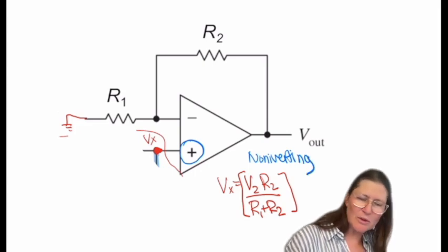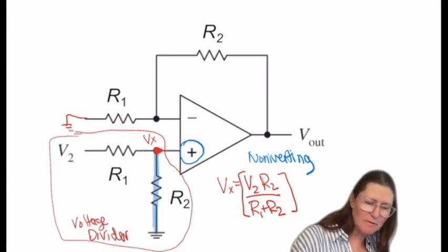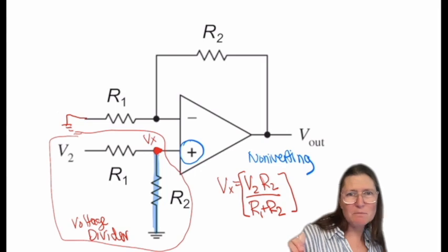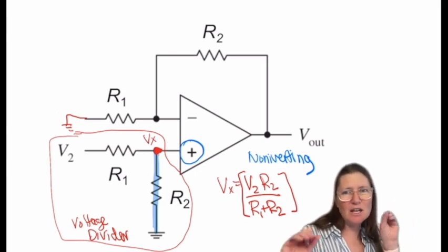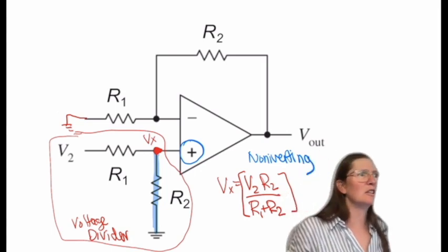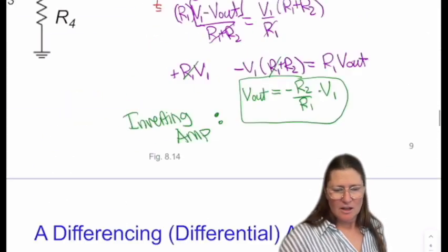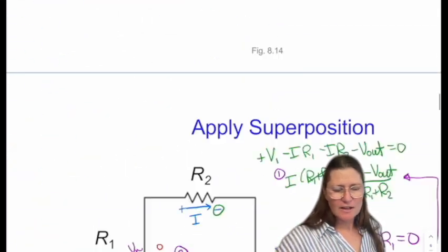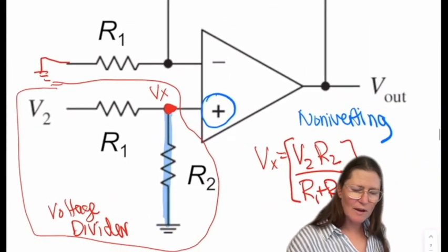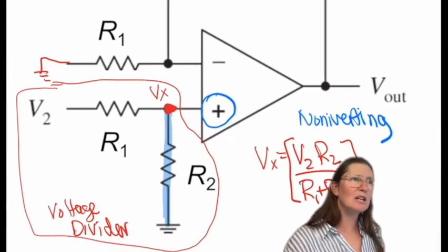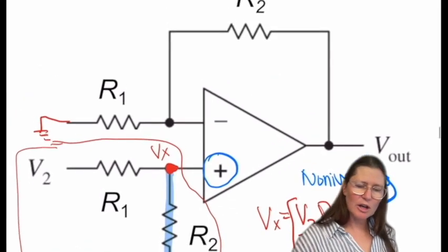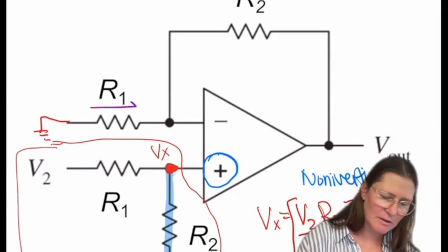So I could go through the same steps that I did before and take out the op amp, equate the Vn to Vp, and then do the one pathway to get that equation. In this case, instead of 0 at Vn and Vp, Vn and Vp are going to equal Vx. So you have a slight difference there where your current, let's write it really quick.